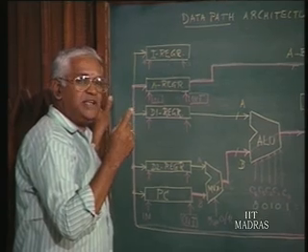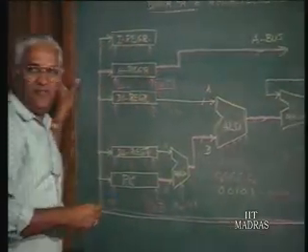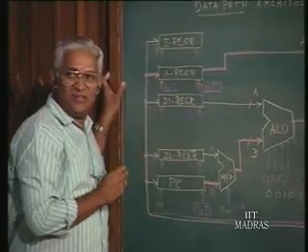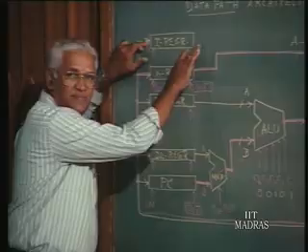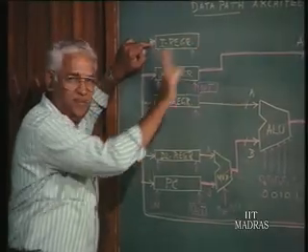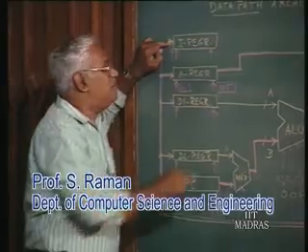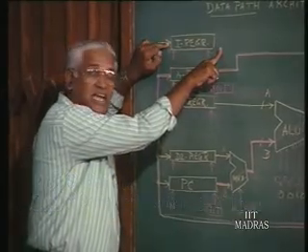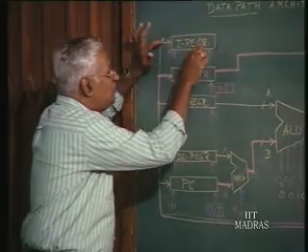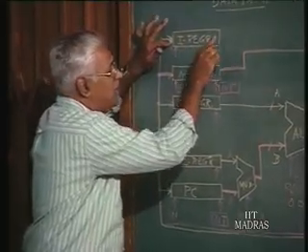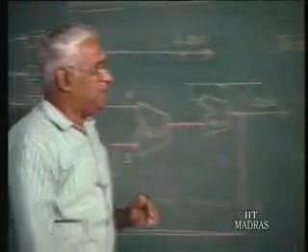As I mentioned earlier, that instruction must come in 3 steps, which means 3 machine cycles. Once the entire instruction comes in here, then it can proceed. Well, it all depends, but the very first byte which comes into the instruction register itself will give some information to the processor. So once the instruction is fetched into the processor, now this will be given, I will write it here.